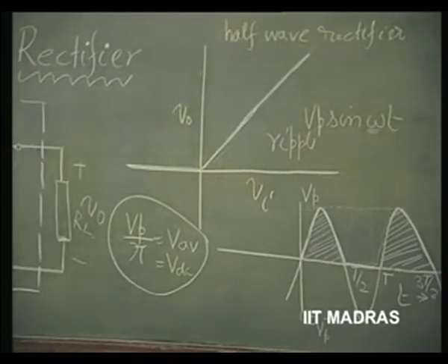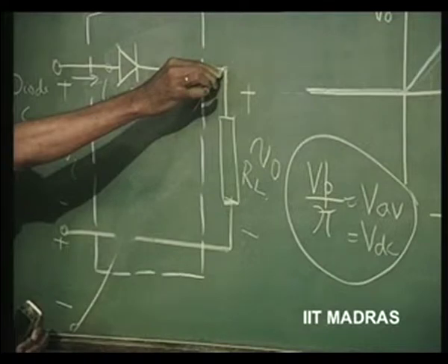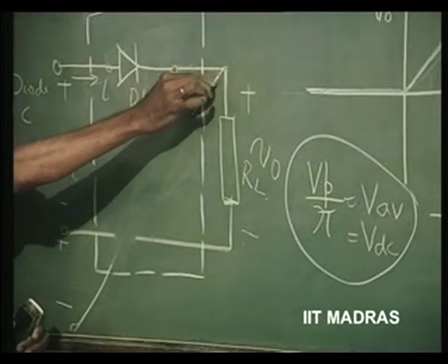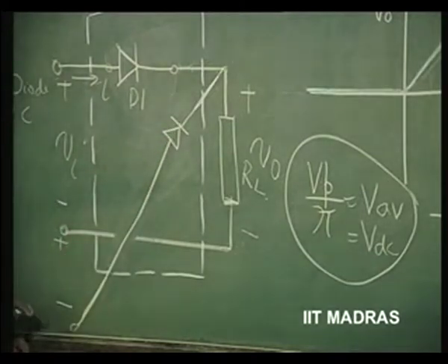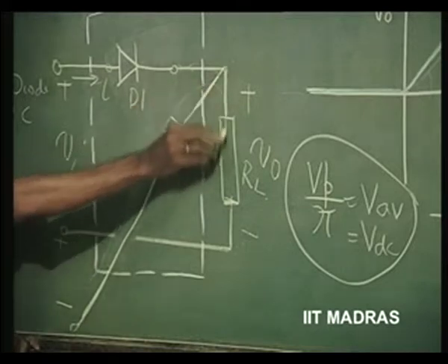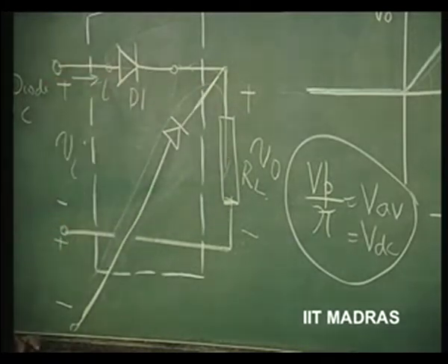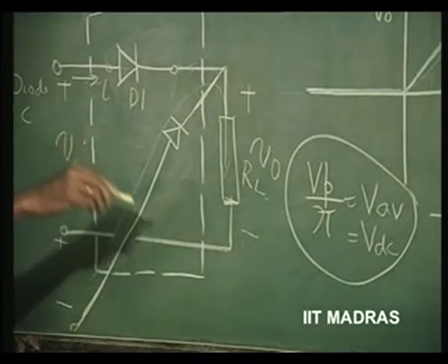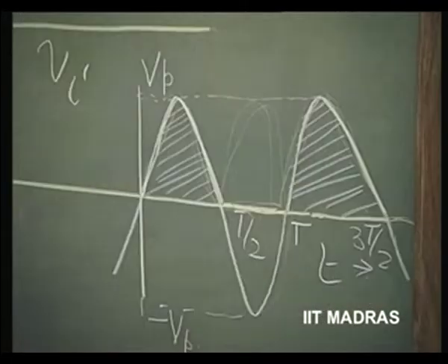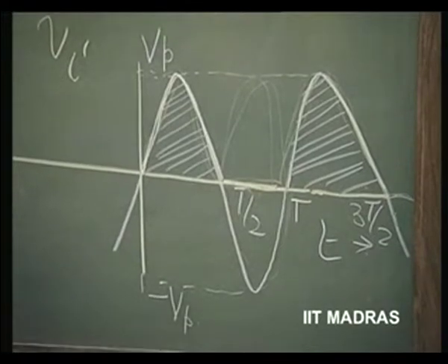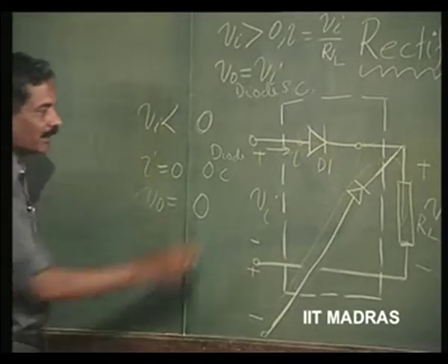Again, what it means is I have to have another diode here in such a manner that it is going to conduct when this is going to be positive and this is going to be negative, such that this diode pumps in current in the same direction as this diode, but when the voltage is in the opposite direction, such that on both the half cycles we have an output. That can be done by using at this particular point what is called as a transformer.